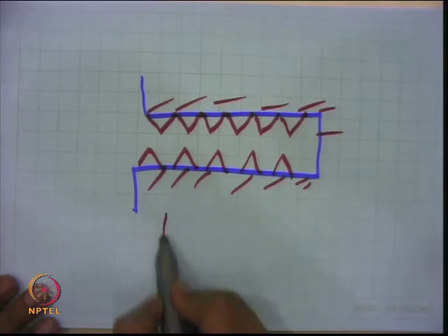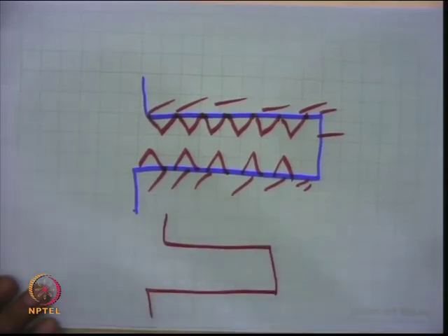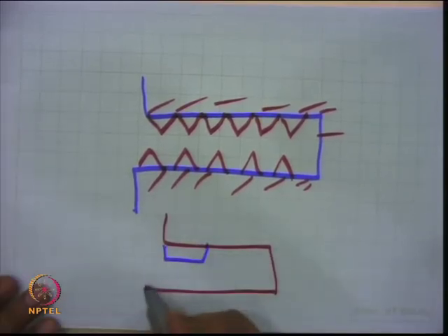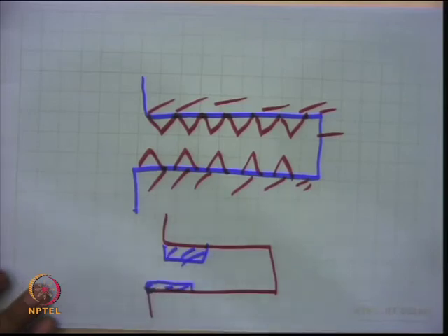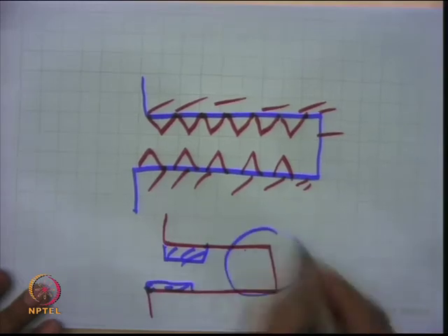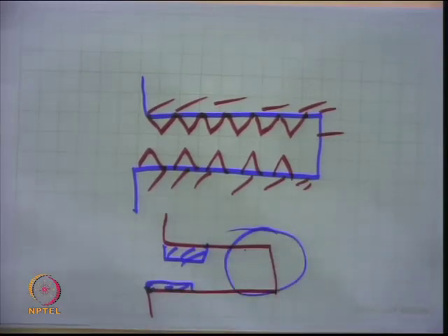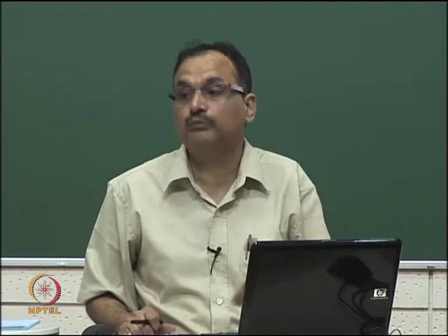The second case may be that it is deposited just on the outer periphery, say only this surface is covered, at low drying rate, and when it is extreme, everything may go to this side at the pore end. Depending upon that, the active metal may be deposited just at the outer mouth of the pore, at the end of the pore, or it may be uniformly distributed. So, the rate of drying is one of the factors which decides this.